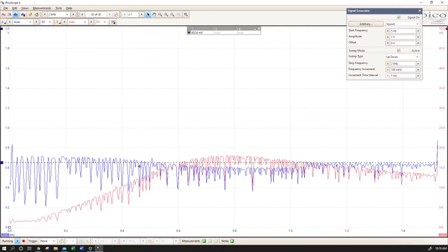The reason we see a trough with the whole circuit voltage, part of that has to do with the sag of the Picoscope. As we get to resonance, the overall impedance of our circuit decreases, and the Picoscope can't supply the current, so the voltage actually sags. So as we hit that low impedance, in this case at that frequency, we're relying on the non-stiff nature of our source to help us identify where resonance is.